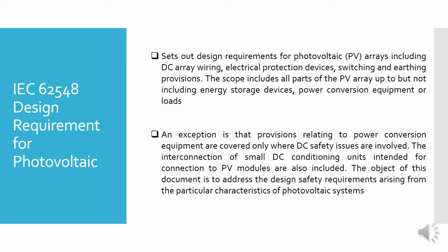For the continuation of commonly used standards and codes in the electrical industry, we have IEC 62548, which is the design requirements for photovoltaic. This code sets out design requirements for photovoltaic arrays including DC array wiring, electrical protection devices, switching and earthing provisions. The scope includes all parts of the PV array up to but not including energy storage devices, power conversion